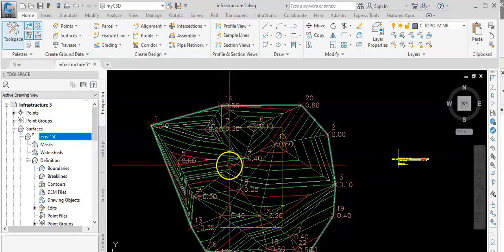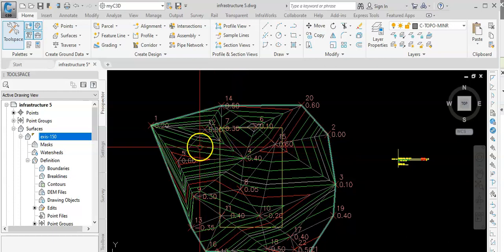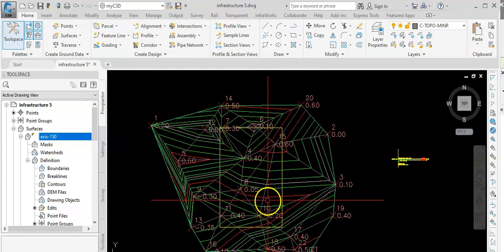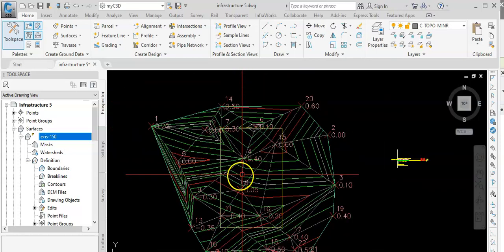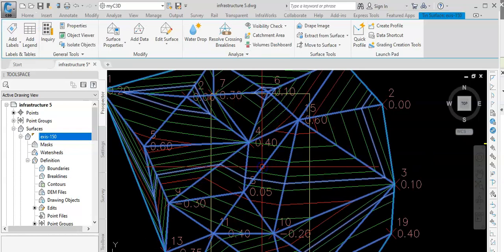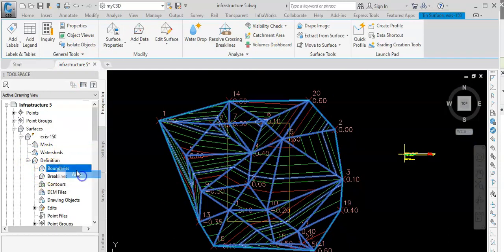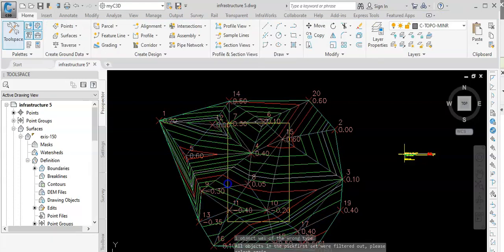So why did I plot this size of the building? It is for the program to work out the volume to the minimum area. If we don't do that, it will give you the volume for the whole survey area, which is much bigger than the building site itself. So the program will eliminate one of the surfaces. Now let's pick the one which is the -150, and we will limit that into this area here.